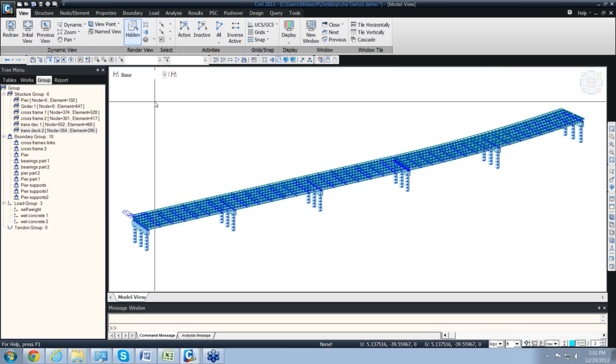Yeah, I mean, they are required so that the bridge has a transverse stiffness that is contributed by the deck. So when the deck appears in the longitudinal direction, it should also have the stiffness in the transverse direction, and that's why we have the deck members in the transverse direction.